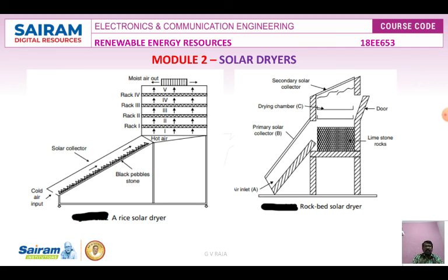So the system removes the heated air from the panel and passes the air into the drying chamber. A sensor is installed in the airflow and uses thermostatic control to turn off the incoming airflow when the temperature is not high enough for solar heating. The existing system operates, and during standby the conventional fuel system can also be used on non-shining days, cloudy days, windy days or winter times. So solar heated air can be used to dry the crops.